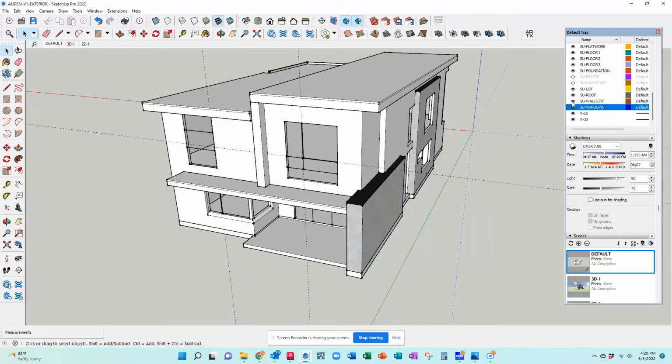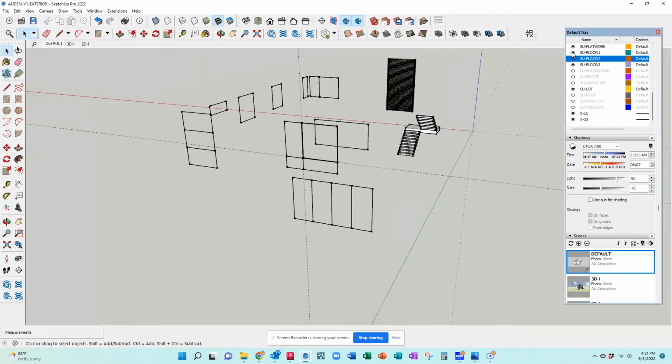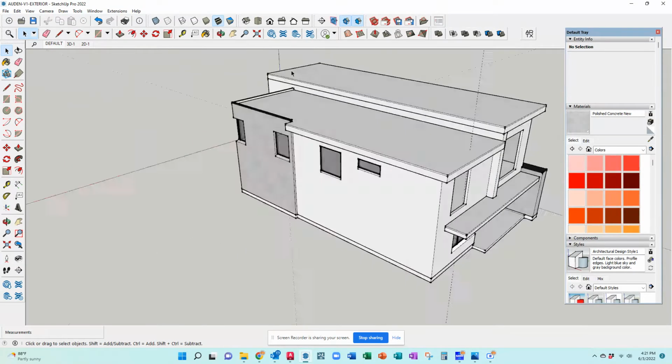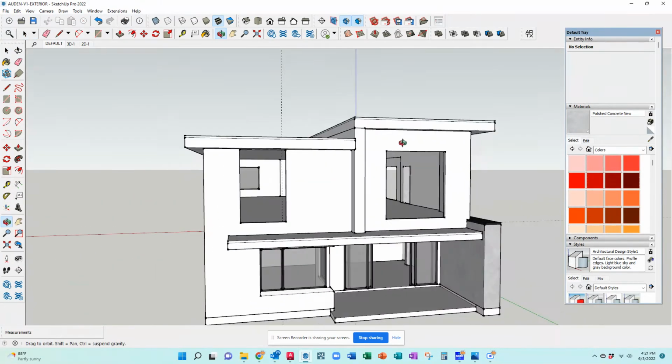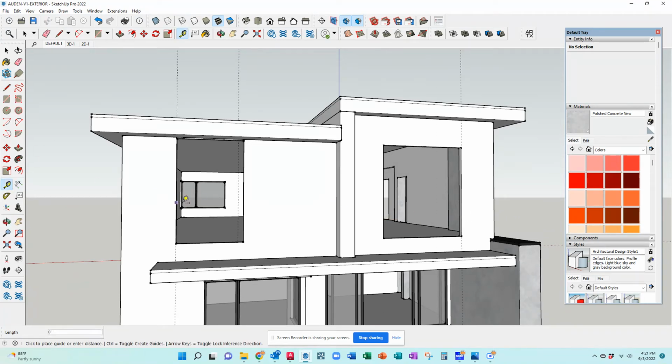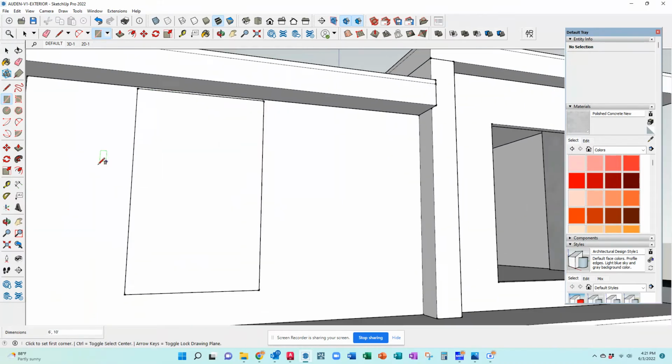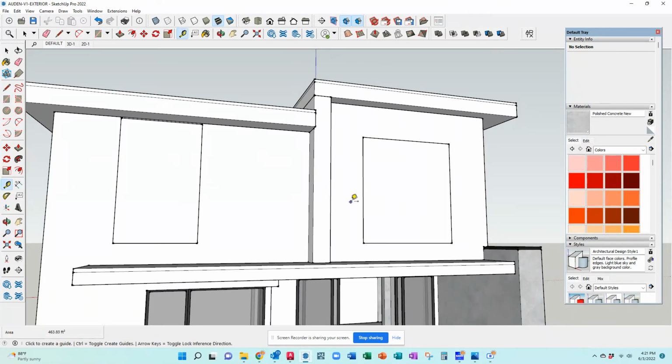Here's the redo I mentioned earlier of the master bath window. Windowizer leaves outline remnants when it turns the window into a group, so we have to turn off all the other layers that we want to keep and erase those outlines to keep the model clean and efficient.